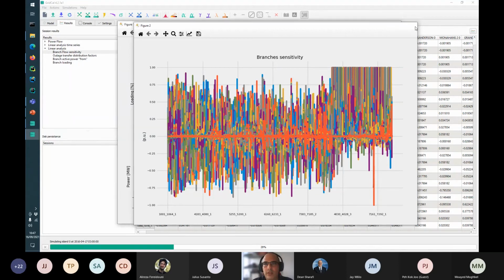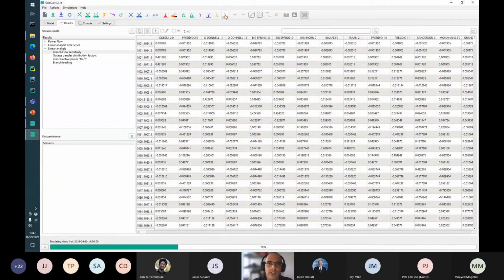And we usually use this for this net transfer capacity. But what if we also want some exotic stuff happening? Like, for instance, we have some HVDC connection between Spain and France. And we have a very exotic control type called the AC emulation, which I haven't heard of in other places, but maybe it exists. That is the HVDC looking at the angles and correcting the flow depending on the angles.